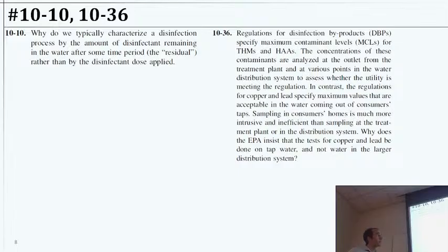Well, as we saw in the cyanide problem, when we have some reaction happening, the rate of that reaction will be determined in a CSTR by the mixed concentration, the one that has already been going through that reaction. When we reach a steady state, we have one concentration, right? That is what's in that CSTR. It's already been diluted since dosing it with all the other water.